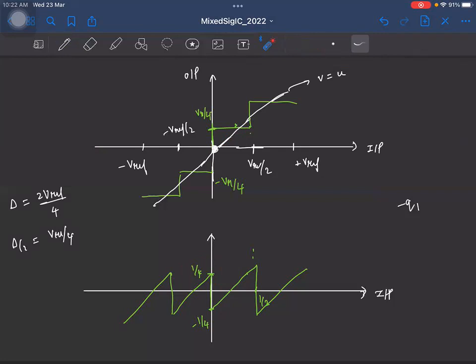As we have seen about ADCs, there will be a lot of non-idealities. If we have a non-ideal ADC, how will the characteristic look like? This is the ideal characteristic. Now, if we have some non-ideality, what will happen? You'll have gain error, offset error, DNL. But the final reflection of all of these errors will be that these transition voltages will no longer be equal to these ideal values. That's the underlying thing. So now let us say, for example, this transition voltage shifts to this value.